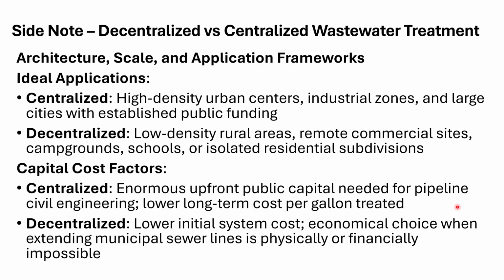A centralized system, ka-ching. It's either built up over time, or if you're putting in a subdivision or expanding a wastewater collection network for a municipality, for a new subdivision or area that you're annexing, what have you, that's a lot of upfront money that you have to spend on capital projects, on installing the collection lines, on rights of way, on lift stations if they're needed, manholes, what have you. So a lot of upfront costs per gallon treated.